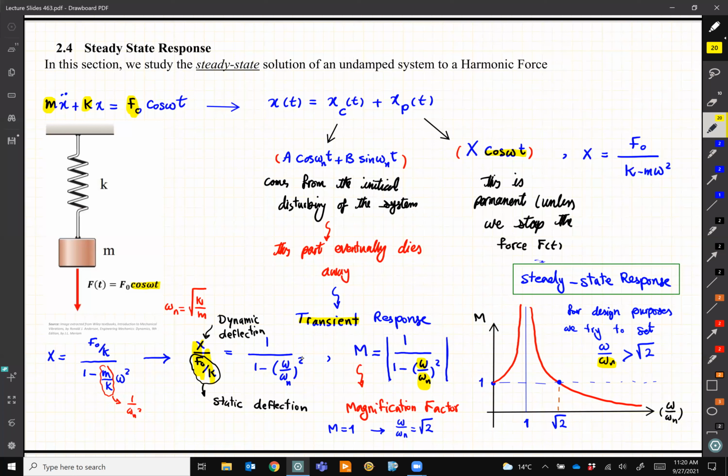And in fact, it is true. In industry, people look at the system, they measure omega n, because in industry for big machines, usually we measure omega n. And that's your last topic in this course, how to measure omega n. We measure omega n, we look at the system, and then we decide, okay, I'm at the critical point, maybe even I'm at 1, that's bad.